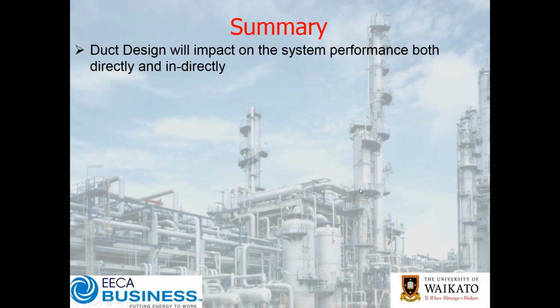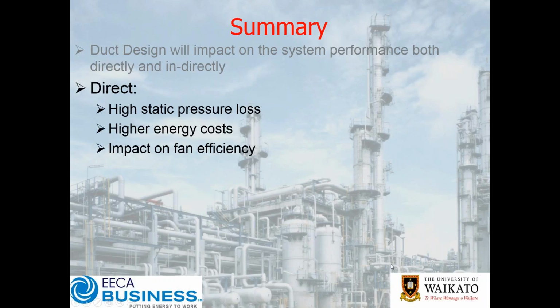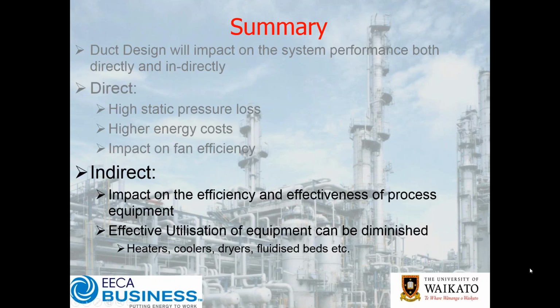Now, duct design will impact on the system performance both directly and indirectly, and I'm repeating myself a little bit here, but very deliberately so. And that is directly, obviously, higher static pressure loss, which is a higher energy loss and may well impact on our fan efficiency. Indirectly, though, you're going to have an impact on the efficiency and effectiveness of your process equipment. So things like the utilization of heat exchangers, if you've got poor airflow distribution across them, that can be diminished. Heaters, coolers, dryers, fluidized beds, all of these processes can be impacted.